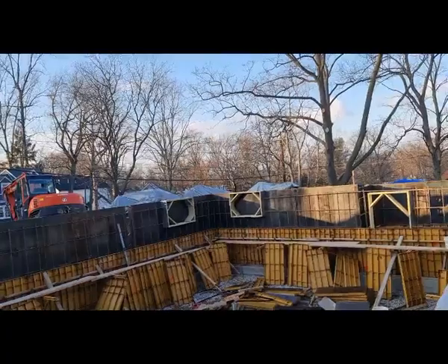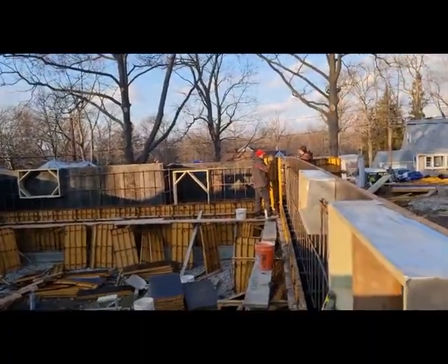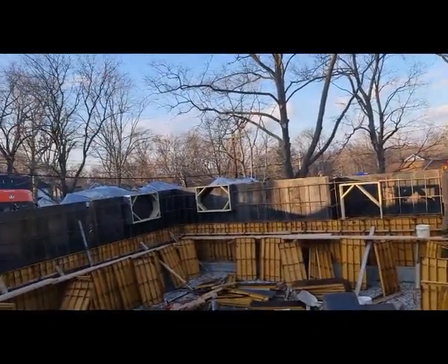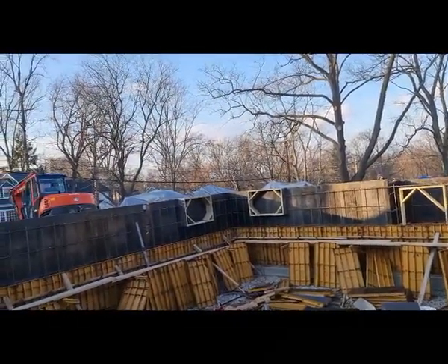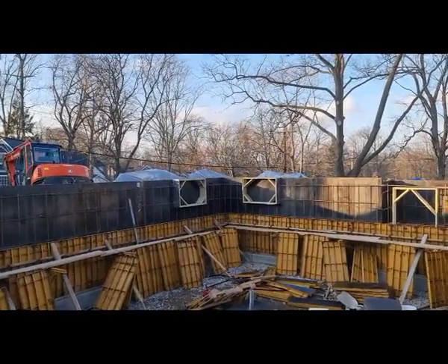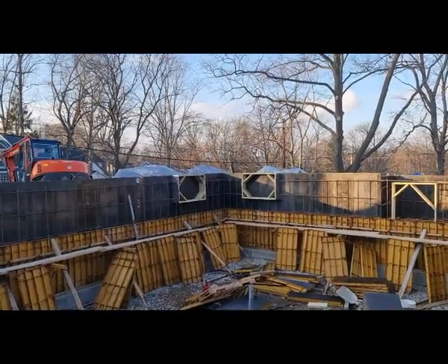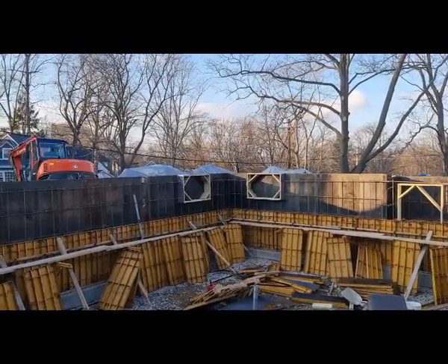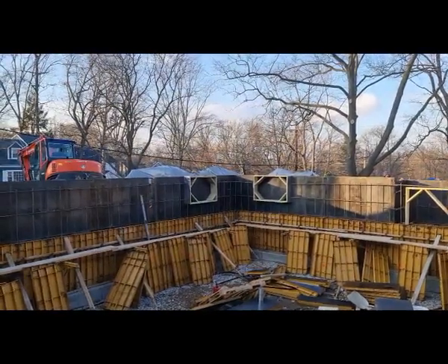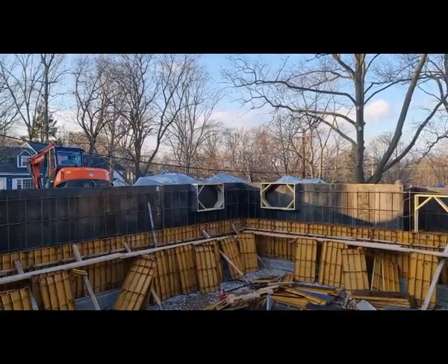This is a 10-inch concrete wall. It will cost you a lot of money to get a professional concrete company to cut it for you. So make sure you go over all the openings with your contractor. Also, one thing that is very important is the sewer connection. I got lucky here. We have the sewer lower than the footing because the house is not on a flat lot. So we're going to be able to dig under and connect to the sewer.